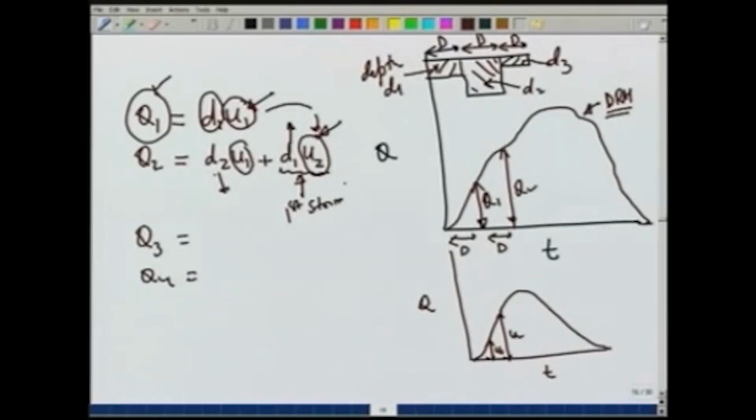So, the procedure is simple, but sometimes it leads to oscillations, and the computed ordinates u1, u2, u3, u4 as we go towards the tail, towards the end, some of the u's may become unrealistic, some of them may become negative, because we are going in a sequential order, and any errors in the computations will add up and will cause non-physical behavior of the curve. So, sometimes we just fit, even if we get negative values here, we just fit and make it a smooth curve which has a unit area under the curve.